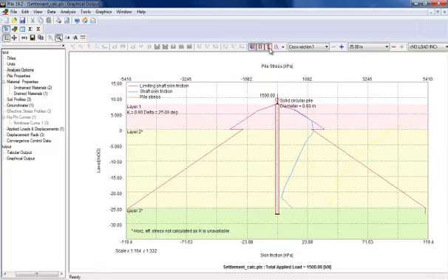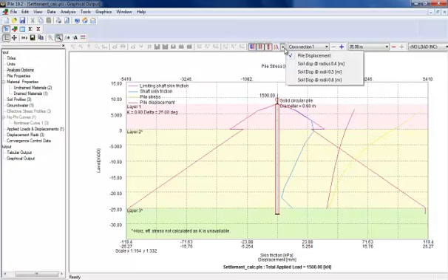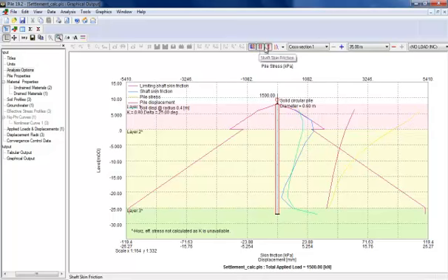We've got the pile stress, and as well as the pile displacement, you can actually find the soil displacement at a certain radius away from the pile. So say I've got a 600 mil diameter pile here. If I maybe go 0.4 meters from the central radius, I can have a look at the behavior of the pile and the settlement, and also what's happening with the limiting shaft skin friction and the pile stress.